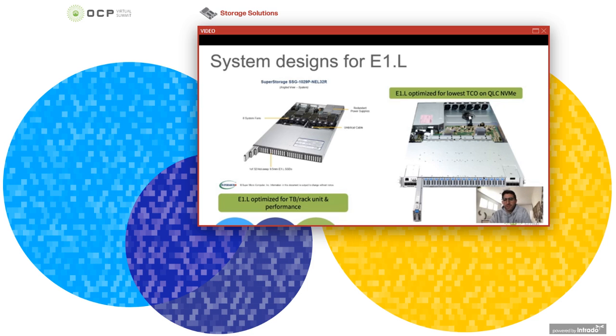This is one of the other OCP inspired designs that you can find on the OCP website. It's a server from Wiwynn that uses the 18 millimeter version of E1.L. So again, for a standard by 4 SSD that's 25 watts, this is probably a little bit overkill, but it's a little bit better for TCO because you can run the fan speed a little bit lower. As you imagine, an 18 millimeter heatsink versus 9.5 can just dissipate a little bit more power. But we don't expect this one to be mainstream going forward. I think we are seeing most of the interest in this 25 watt E1.L around 9.5 going forward. But the spec does call out both of these, and certainly whatever designs are interesting.